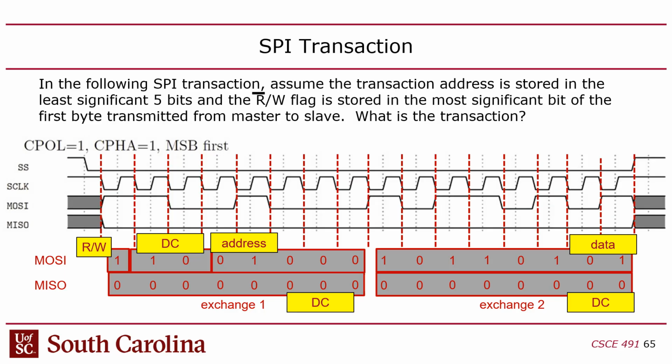Okay, yeah, that's a good point too. So flash memory uses SPI, right? Seems like a bad choice because, as I mentioned, SPI is not really set up for reads and writes of addresses. So why would you use that for flash? It's not a very efficient way. But it turns out flash is typically interfaced with SPI. And it uses quad SPI, so you have 4 data lines, so you get parallel communication, a modification of the standard once again. So if you want more bandwidth, you can have multiple channels, multiple lanes.